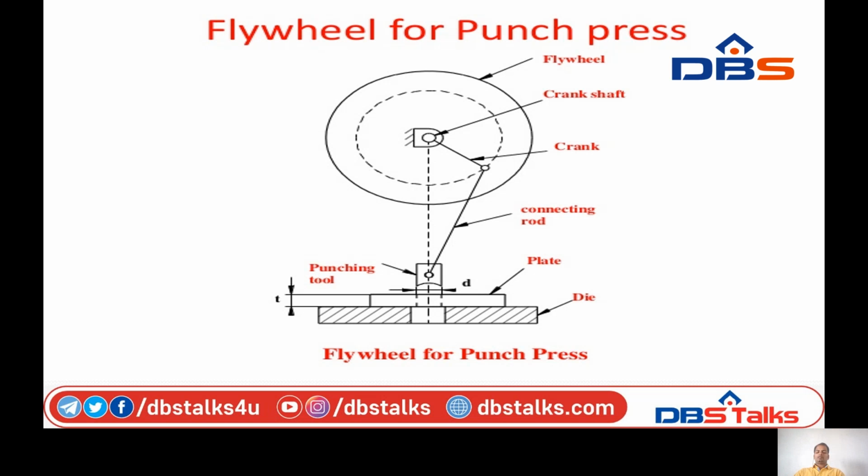So a punching press is shown in the figure. The crank is driven by a motor which supplies constant torque, and the punch is at the position of the slider in a slider crank mechanism. From the figure we can see that the load acts only during the rotation of the crank, that is theta, between theta 1 and theta 2, the angle of motion of the crank.